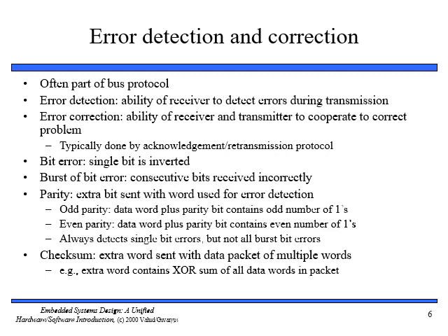Parity is a single bit of information that is sent along with a word of data by the transmitter to give the receiver some additional knowledge about the data word. This additional knowledge is used by the receiver to detect, to some degree, a bit or burst of bit errors in receiving a word. Common types of parity are even or odd.